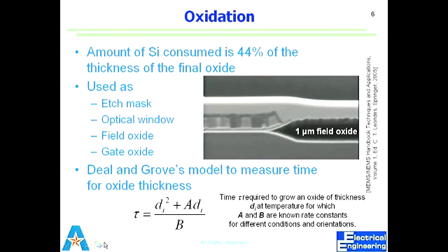Again, ideally, that reaction should be way slower than the reaction with the material that we really want to remove, right? So this is the word selectivity. For any etch, we are always worried about the selectivity of the recipe.